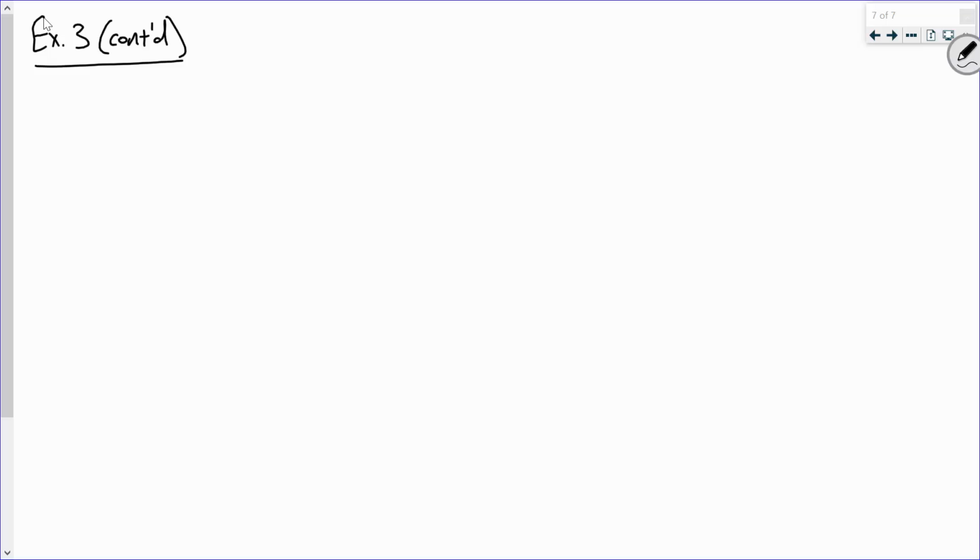So what do you think the first thing we need to compute is? Let me ask it like this. We're trying to determine how much load it can be subjected to before it cracks. How do we know when it cracks? When the moment reaches what? The modulus of rupture. So ultimately, we're going to need the cracking moment, right? Everybody okay with that? So we need to determine the cracking moment. And what's the first step in the cracking moment? What you just said earlier? Modulus of rupture. I'm getting everybody woken up. Come on.